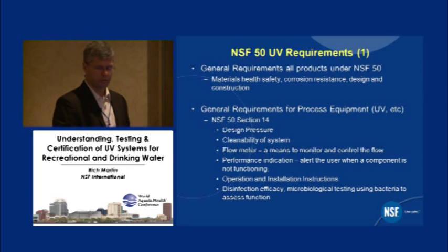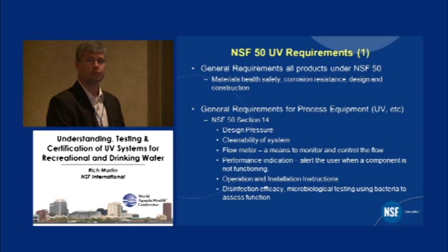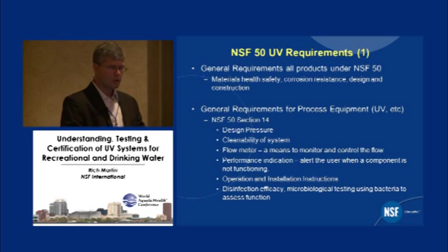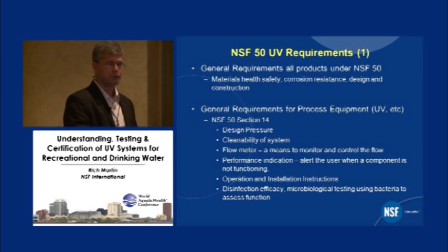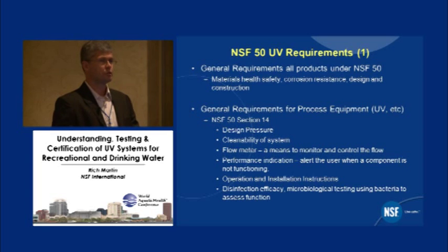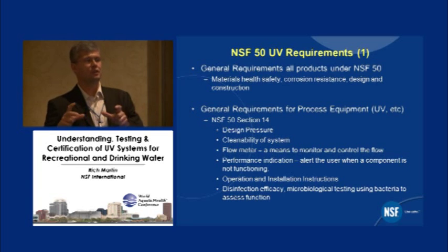So this is just a brief summary of what's in NSF Standard 50 as it relates to UV system testing. Obviously, there's general design criteria, safety and operation protection. There's requirements for a flow metering monitoring system to be installed along with the UV system. That's not to say that you have a flow meter inside the UV system.